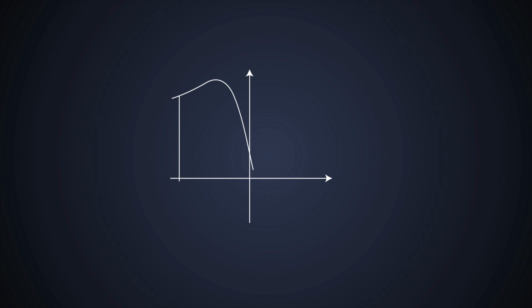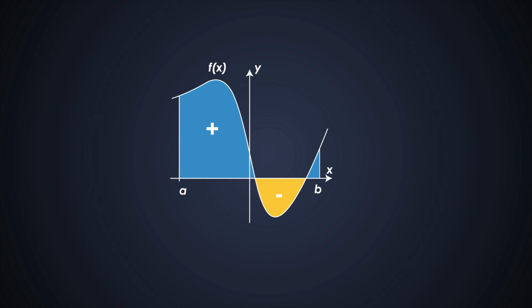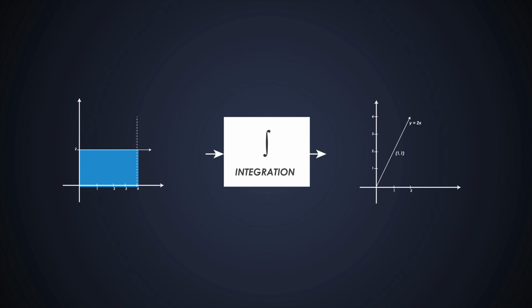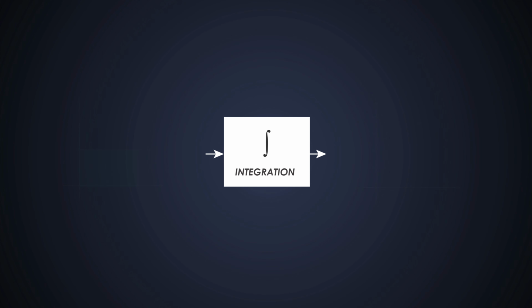As we know, integration is basically the area under the curve. That means when we provide a normal linear curve, its integration will be a ramp output increasing linearly because the area under this curve will add up. With the same logic, if we have a square wave, it will provide a triangular waveform at the output.